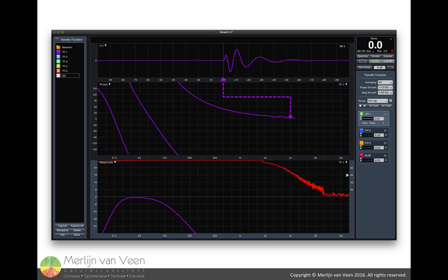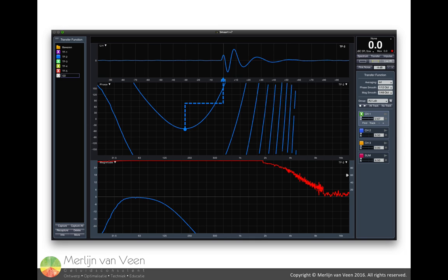Again, in this particular example, we're also synchronized to the beginning of the waveform in the impulse response. That is flat phase, that is T0. However, if we move along the impulse response, now the phase trace around 250 Hz has become the flat portion of the phase trace, marking T0. And the frequencies to the right, 250 Hz and up, are leading, and the frequencies to the left, 250 Hz and down, are lagging.